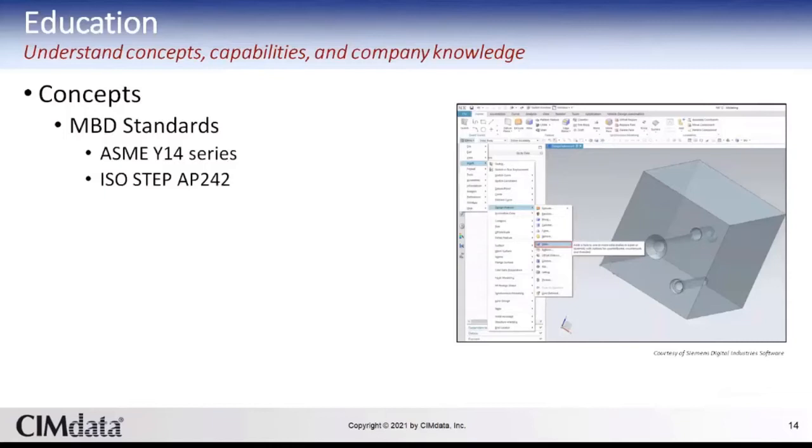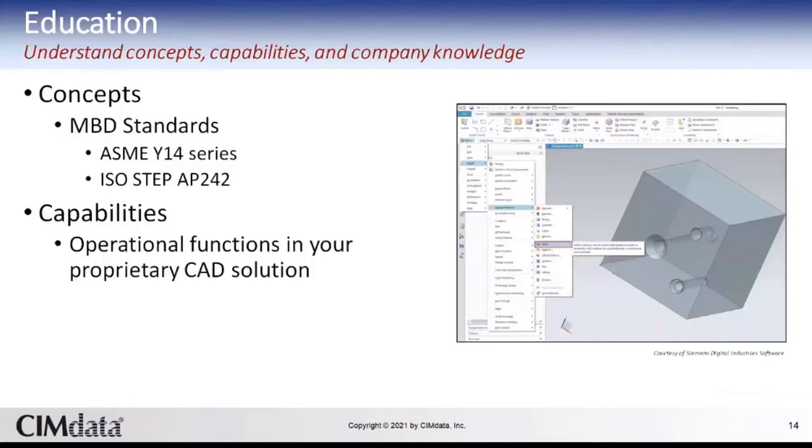First step is to put together a transition team and educate yourself. You should really focus on three areas. Number one, model-based definition and PMI concepts. The standards are presented in the ASME Y14 series of standards and ISO STEP AP 242.